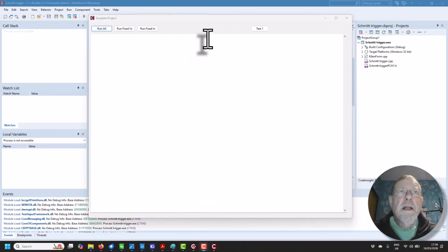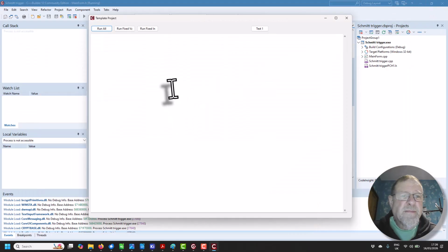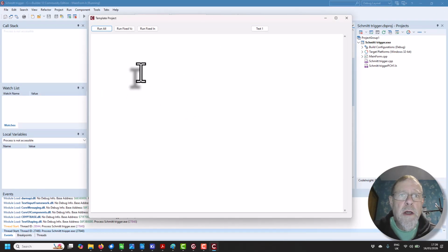Okay, here we go. Here's my hacky little program just to solve the equations and get the resistors out, in this case R3, R4 and R8. I put our new reference voltages, what we called Zener voltages, in, and you put one of the resistors in and it'll find the other two to suit.